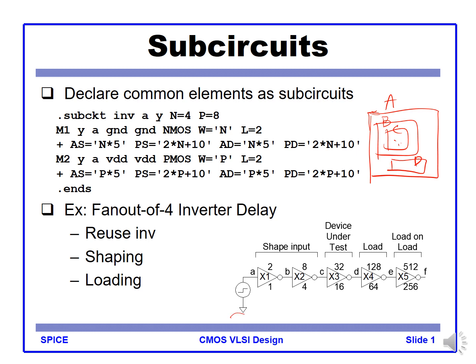So for example, for this kind of circuit, each inverter has a PMOS and NMOS inside. So this kind of instance is the sub-circuit. We define that inverter with the sub-circuit definition, starting with the .subckt. The sub-circuit needs to have an input and output. So input port information here, and this is the property we want to pass on to the sub-circuit.